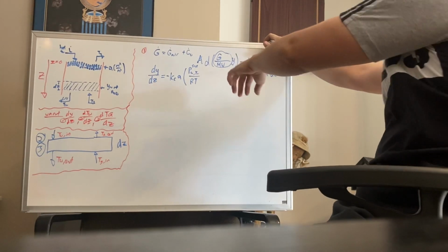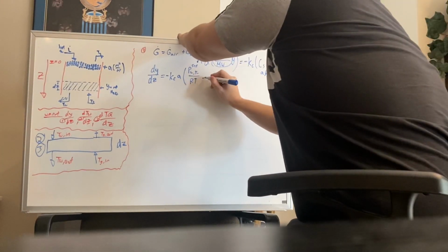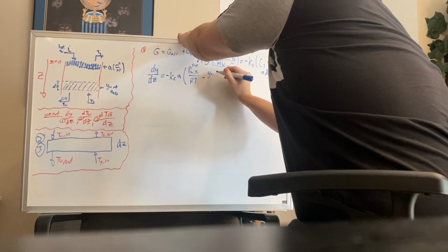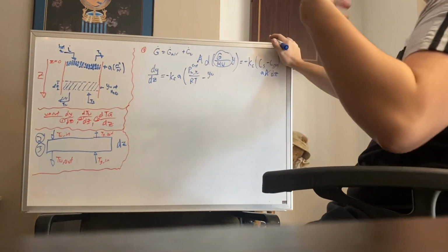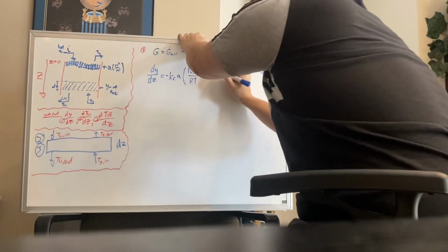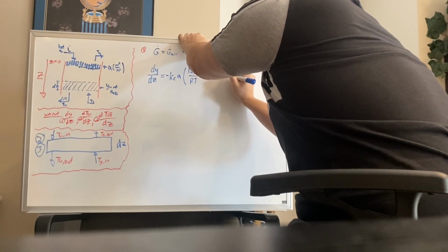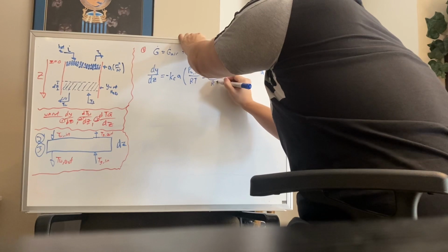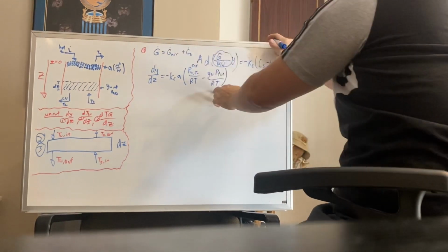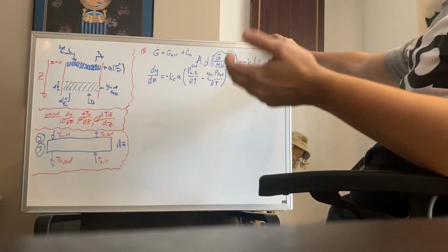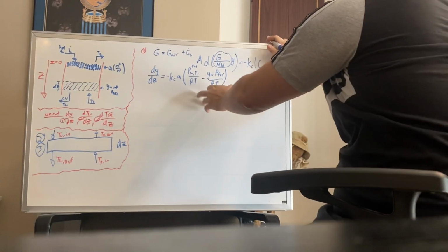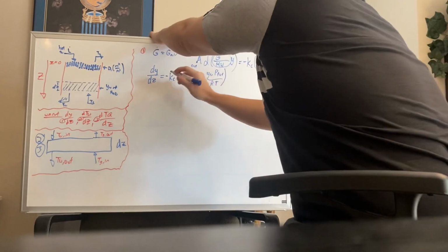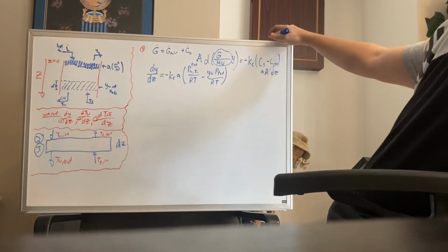And then this is going to be subtracted by the mole fraction of water in the cooling tower at that moment. And this is going to be multiplied by the total pressure, all over the same gas constant times the temperature. And this is pretty much what is going to have you left with your dy dz value.